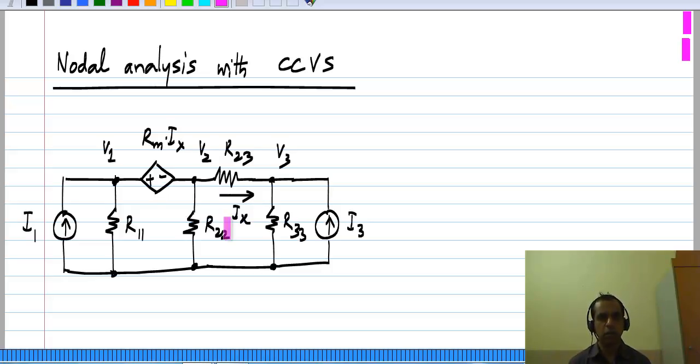So now what do we do? As usual, when you have a voltage source, the problem is that you don't know the current through it. Meaning, you cannot write the expression for the current as a function of the voltage across the voltage source. The voltage across the voltage source is defined independently of whatever current is flowing through it. So we eliminate those currents altogether by forming a supernode.